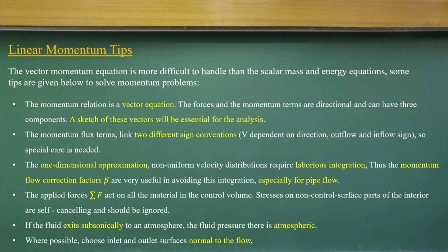You always look at the velocity directions, whether it is inflow or outflow, and at the dot product, the scalar product of the velocity and the normal to the control surface, whether it is a positive or negative sign. Always try to draw the velocity diagram first.